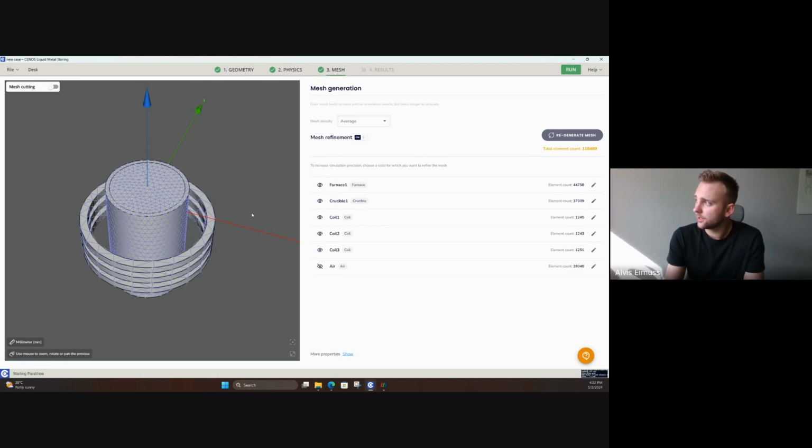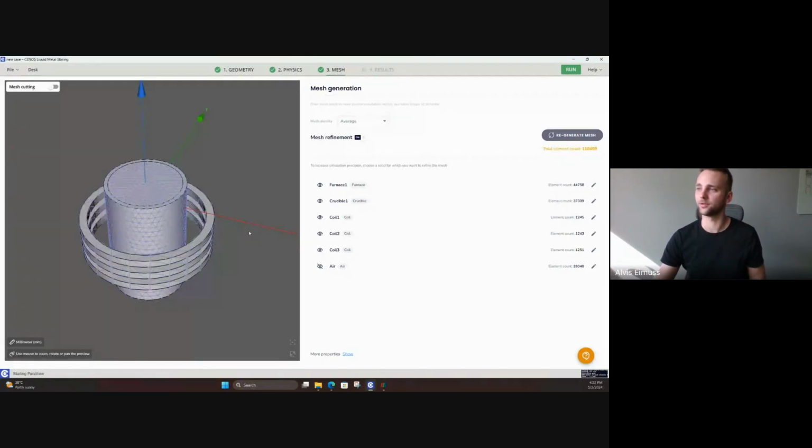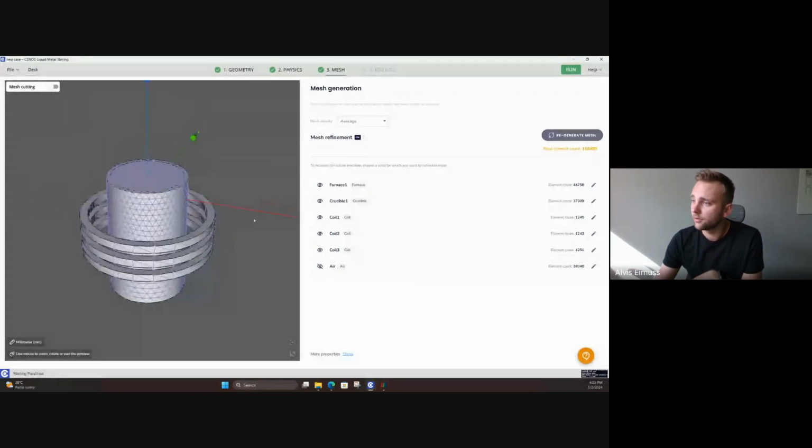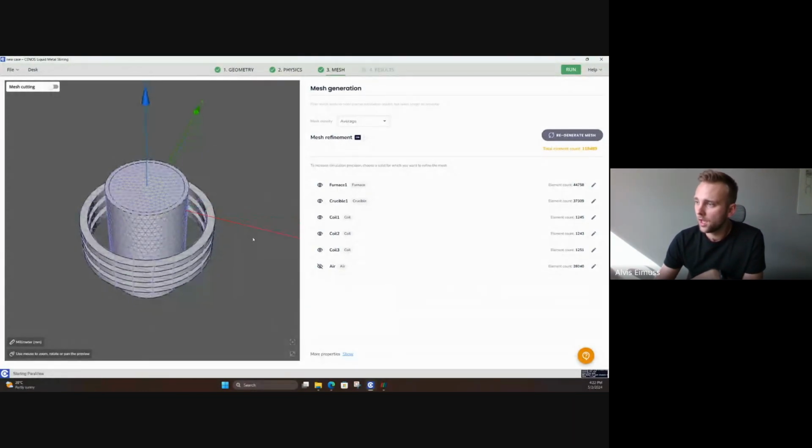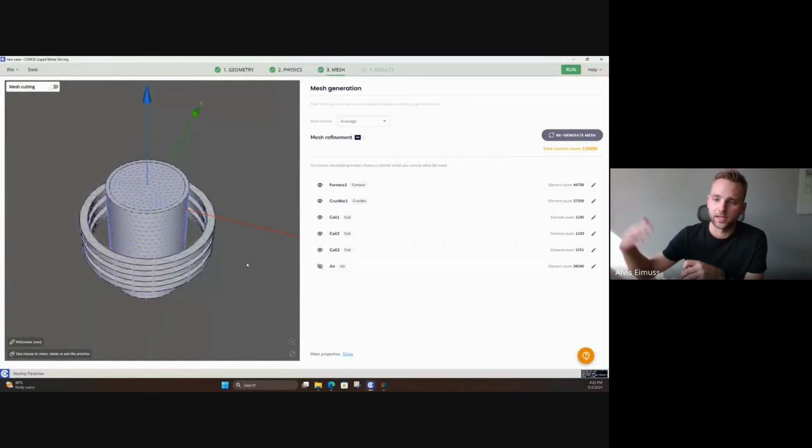At this point, we could run the simulation, which I'm not going to do at the moment, simply to save some time. But I have already calculated the results of this case. Once the simulation is done, results will pop up in a separate window in one of our third-party tools, ParaView, with already some pre-made customization. During calculation, you will also get some information about the progress, things like minimum maximum temperatures, so you can actually follow the mixing process as it is being calculated.